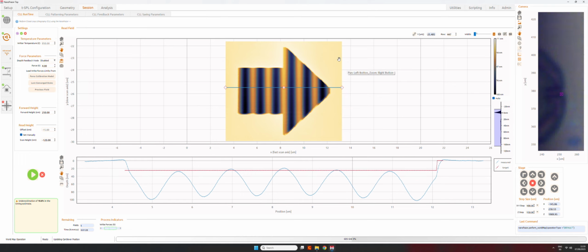A nice use of the temperature map is for patterning on insulating substrates. So the concept behind it is that there is a thermal bending associated to the cantilever being heated up. So when we are heating up the cantilever, then we're able to bend it.